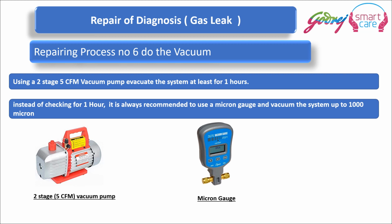Now we do the vacuum using the 2-stage 5 CFM vacuum pump. We evacuate the system for at least 1 hour. Instead of going by 1 hour, it is always recommended to use a micron gauge and vacuum the system up to 1000 microns.